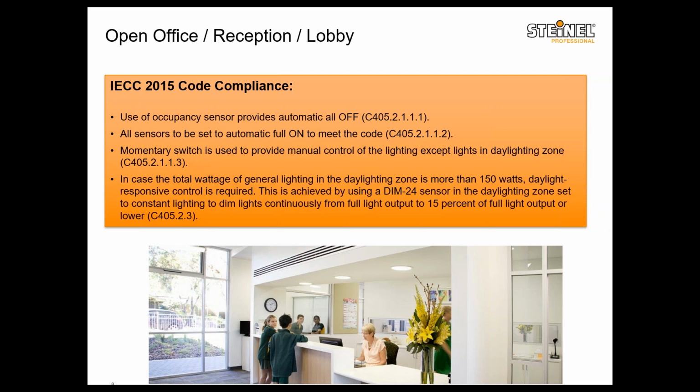And in open office and reception areas, because sometimes you have tall windows and big areas, you're likely to run into that 150 watts general lighting requirement of daylight responsive controls. So this is one of those places where you probably will have to do daylight responsive controls. And in the next slide, we will go into a bit more detail with that.